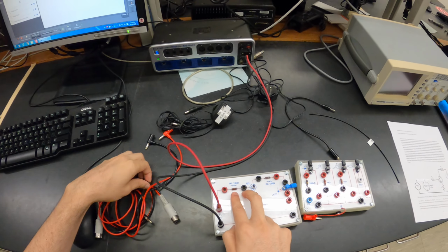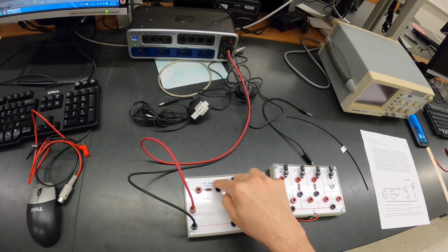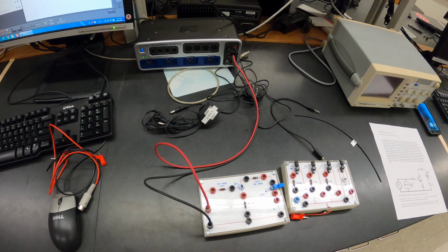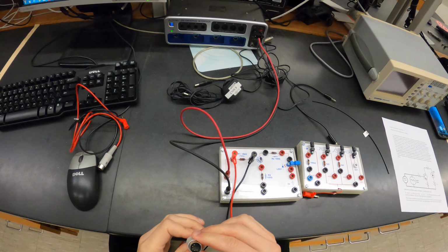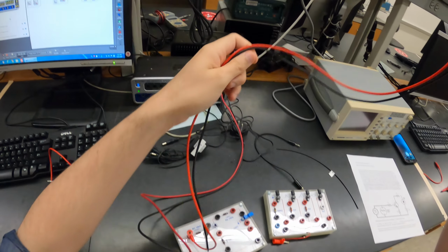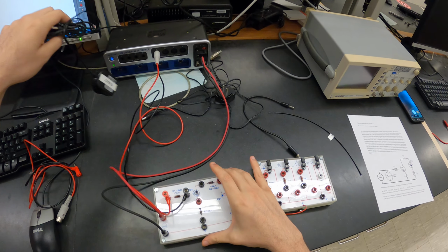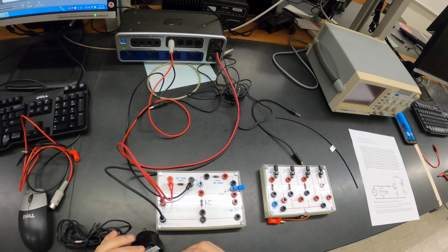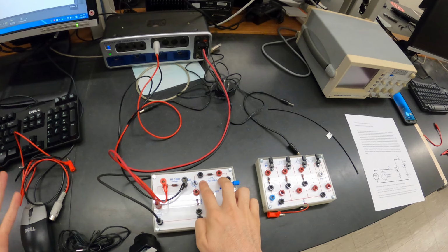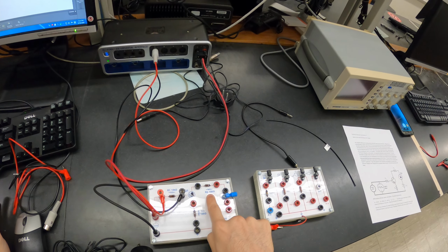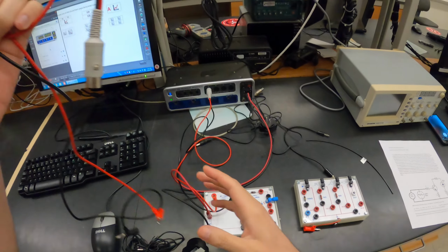So we actually measure voltage, and then we can divide the voltage by this resistance in order to get the current. So again, we connect this here, the other here, and then we connect this to channel A. We'll also be measuring the current across this resistor. Again, we measure the voltage and we divide it by this resistance, 100 ohms, so we get the current.